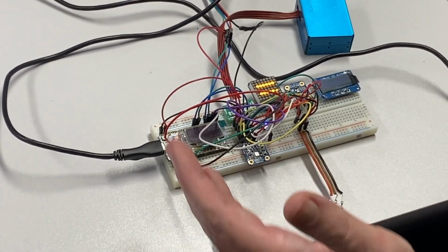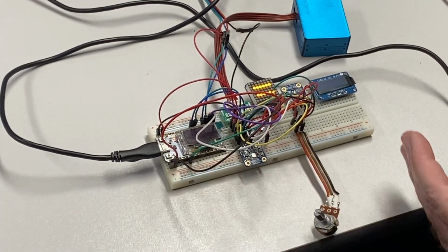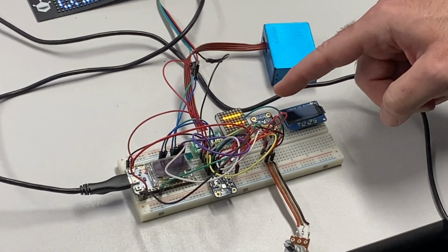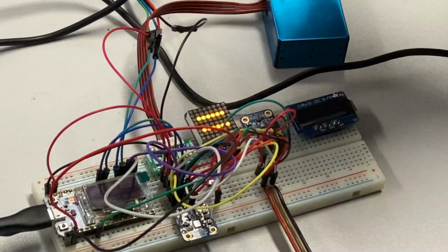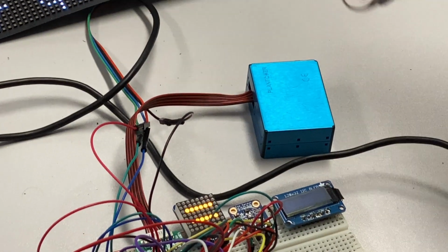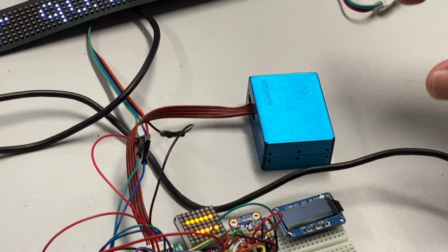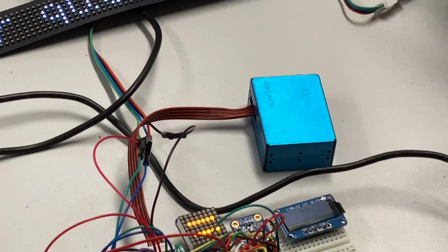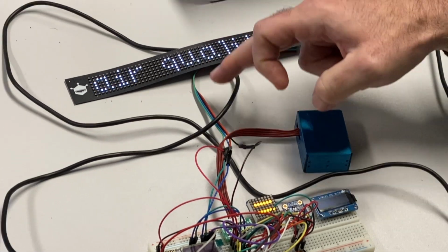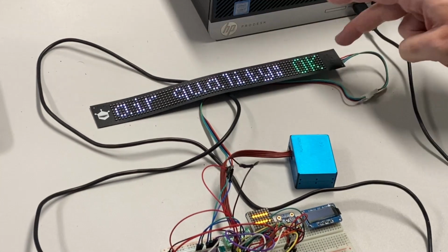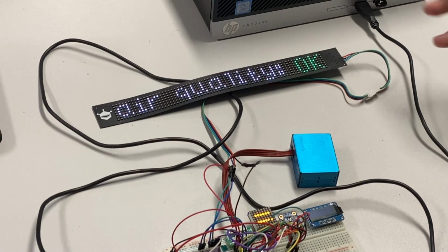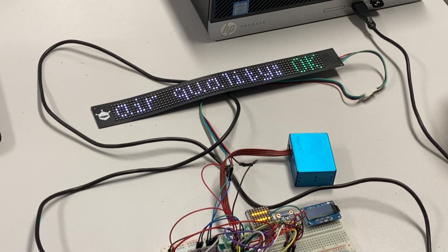client application. And over this breadboard, we have connected to our ESP32 here a CO2 sensor. Also, via this wire to this little blue box, we have a dust particle sensor that measures the number of dust particles of 3 different sizes in the air. And also connected here, via a serial port, we have this LED strip, and this LED strip will indicate if everything is safe with respect to air quality or not.